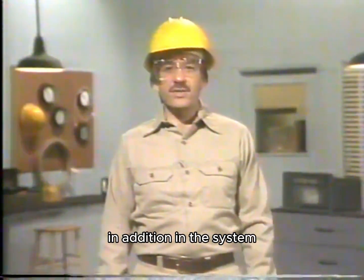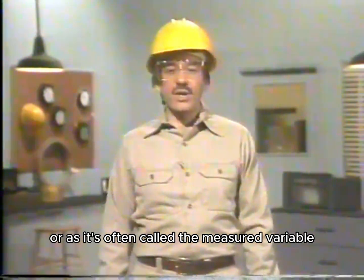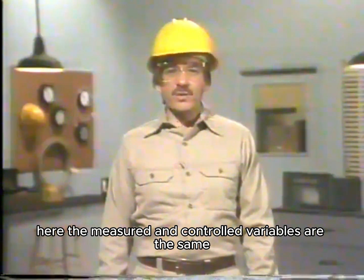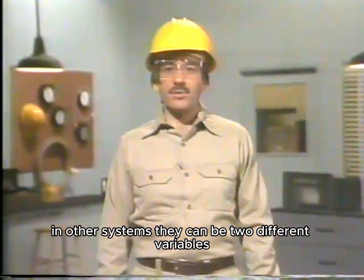In addition, in this system, we're monitoring how much air pressure is in the tank, and the system variable that's monitored is referred to as the monitored variable, or, as it's often called, the measured variable. Here, the measured and controlled variables are the same. In other systems, they can be two different variables, as we'll see later.